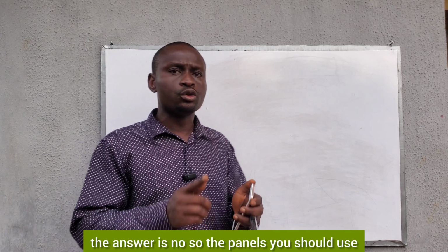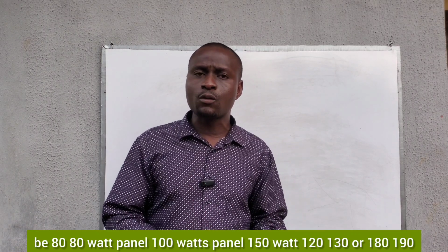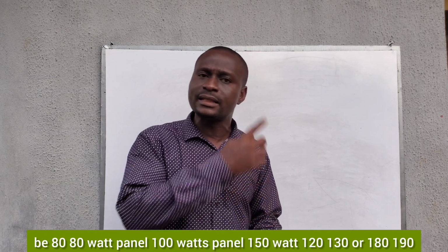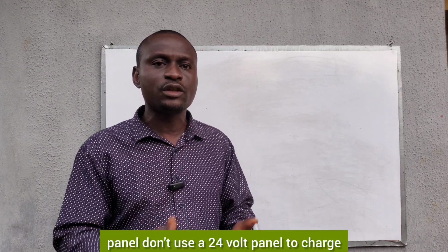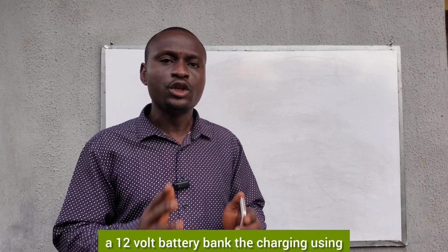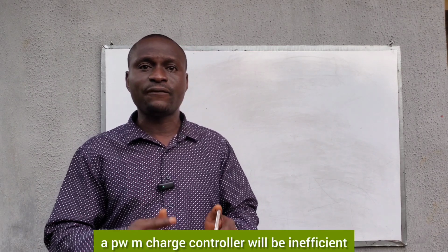So the panels you should use, if you're using a PWM charge controller, should be an 80 watt panel, 100 watt panel, 150 watt, 120, 130, or 180, 190 watt panel, or 200 watt panel. But the 200 watt panel should be a 12 volt panel. Don't use a 24 volt panel to charge a 12 volt battery bank. The charging using a PWM charge controller will be inefficient.